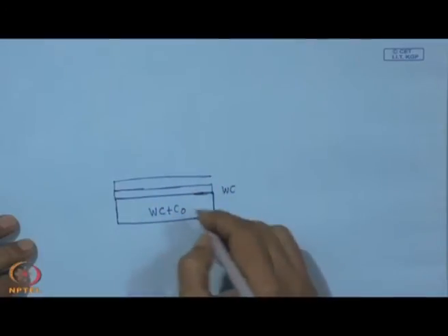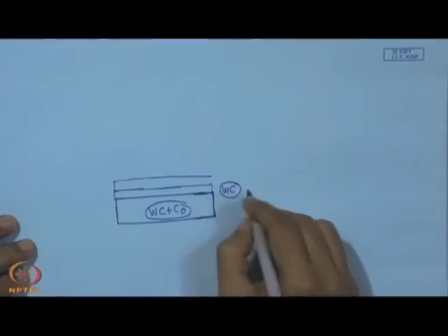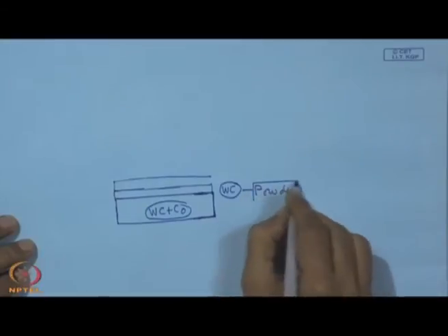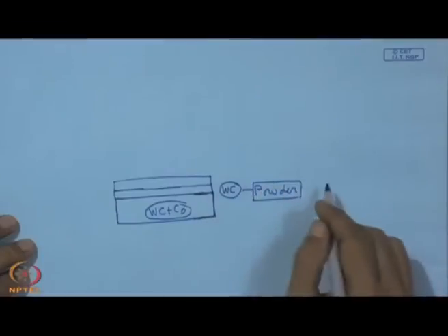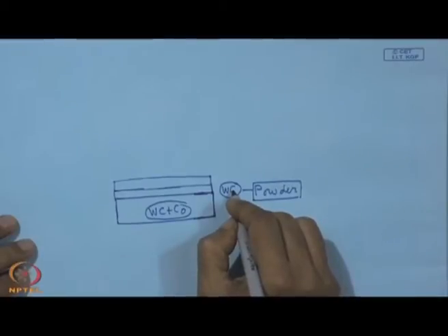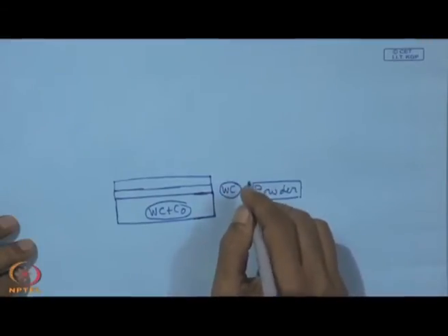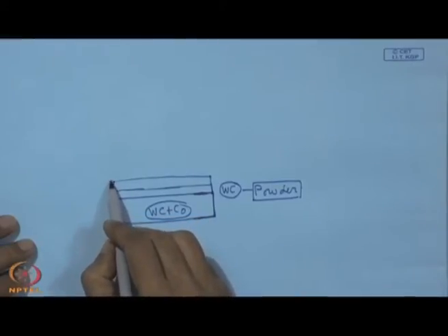So, that means, first we have tungsten carbide cobalt, and then this is tungsten powder which can also be deposited by this plasma spray process, and in the process we can also initiate flow of methane. So, it is going to be a mixture of tungsten carbide with some diamond particles. So, that will be embedded. So, it is a dispersion, and finally, we can also have a diamond build-up over this.